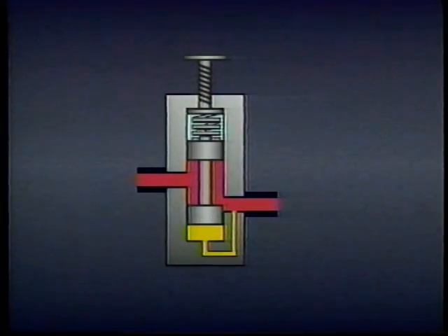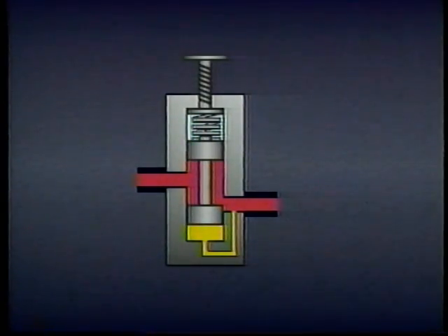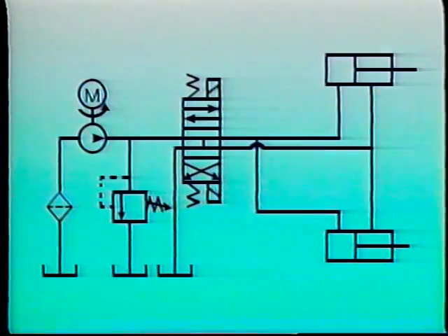If pressure drops, the spring pushes the spool back, increasing the pressure. During normal system operation, the spool balances at an intermediate point and maintains a constant pressure on the secondary side of the valve. A pressure-reducing valve is often used to adjust the force which actuators produce.